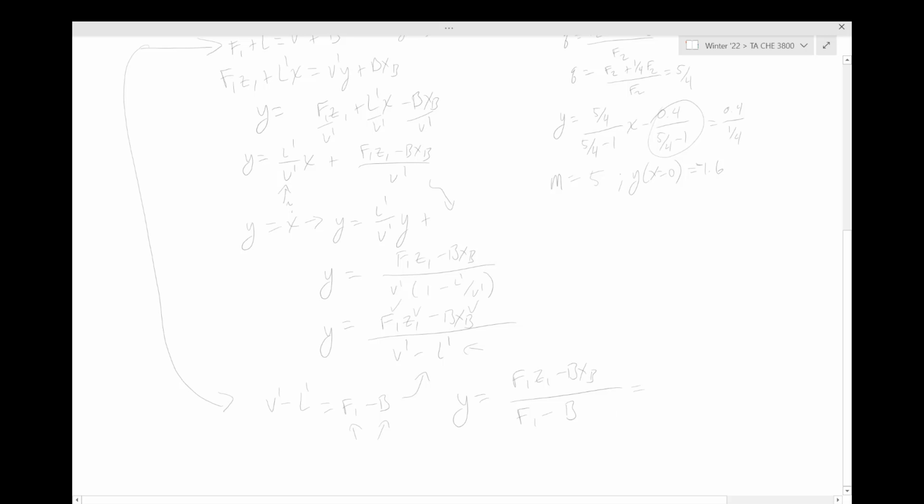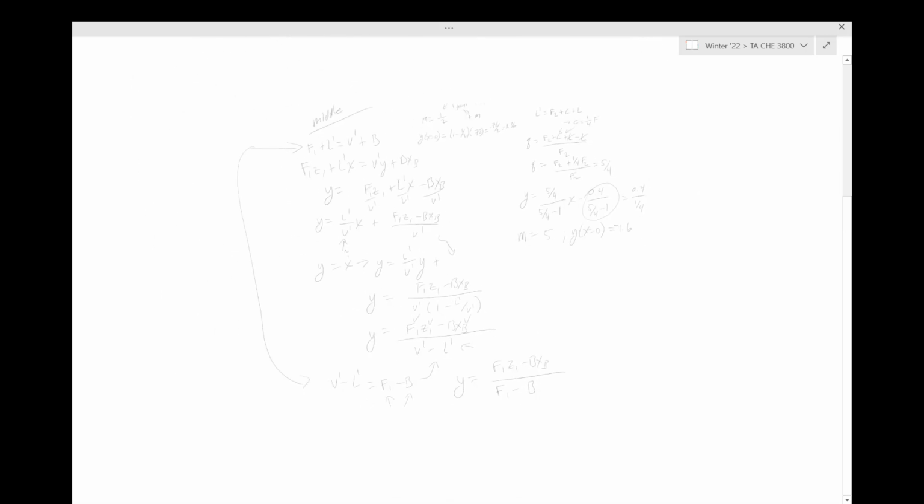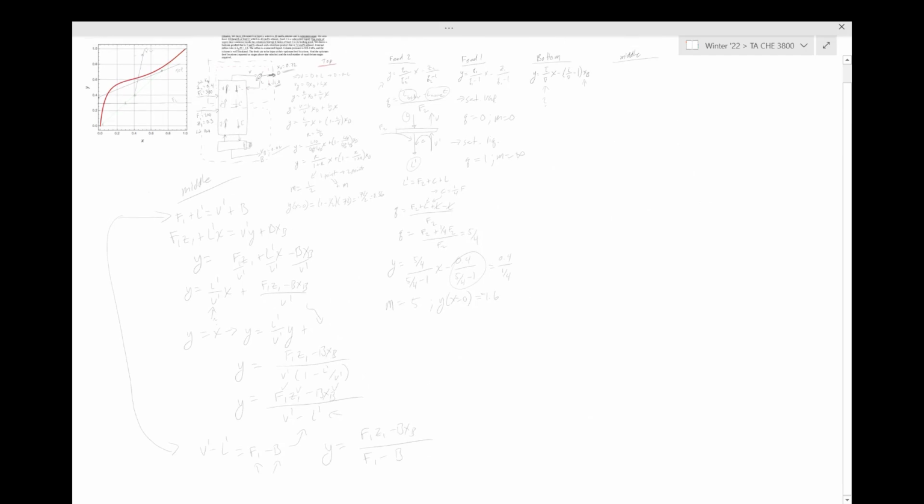So to do this, we now need to do an overall mass balance for the entire system. So to do that, zoom out again, and look at our column. I'm going to block all this off and do an overall balance for the entire column. We know that F2 is coming in, F1 is coming in, and those are the only things coming in. That must be equal to our distillate flow rate plus our bottoms. Again, we know 2 of the 4, so we need another equation, and that one's just going to be the most volatile component equation.